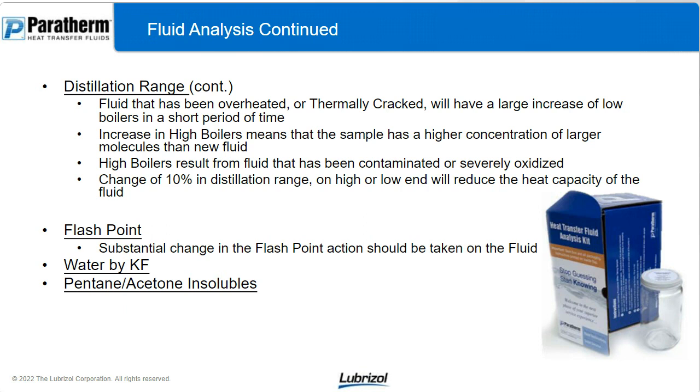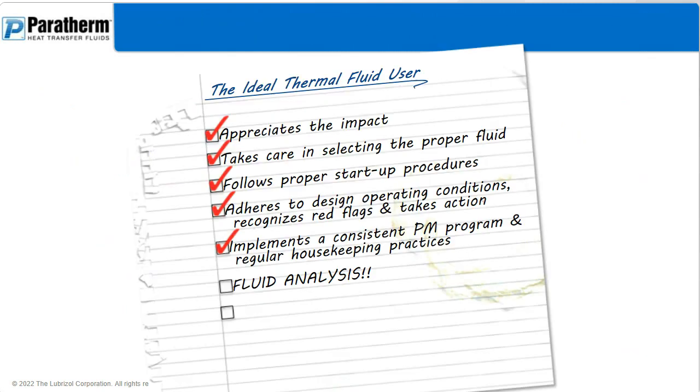Again, flashpoint. I know we said we need to understand flashpoint, and this isn't so much for the safety aspect of the flashpoint itself, but if there's a substantial change in the flashpoint, that means that there was a substantial degradation factor that happened to that fluid. In order to significantly change flashpoint, the molecular structure of the fluid probably changed a lot. So that's just another red flag that we would look at for the flashpoint. And then we can do other tests, like if we consider there might be water in the system, if there's a lot of solid buildups, we can do tests that focus around that. All right, so next aspect, fluid analysis, checked off. Very important. That's why it's capitalized with exclamation points.